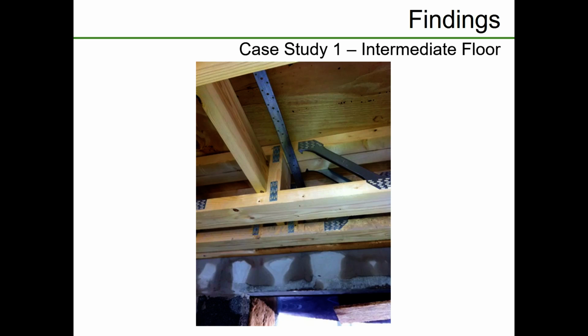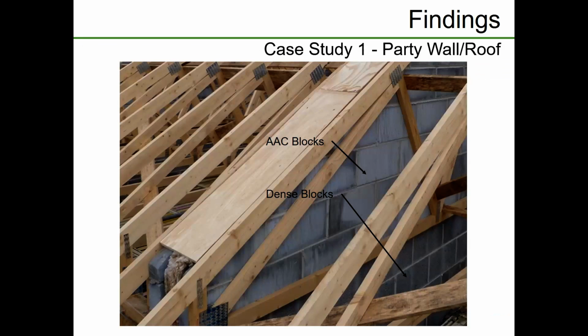And here we've got a timber ledger. This is the contractor's fault. It's a redundant timber ledger. At the other ends, these joists were hung off timber ledgers. They fixed one to the wall here, and it's not necessary. Okay, it was just left in. It did affect the thermal bridging, but it's fairly nominal. But the point is, it's just redundant work. A good example of thermal bridging design, or thermal detailing rather.